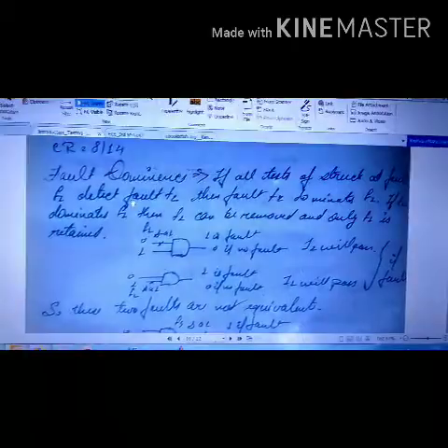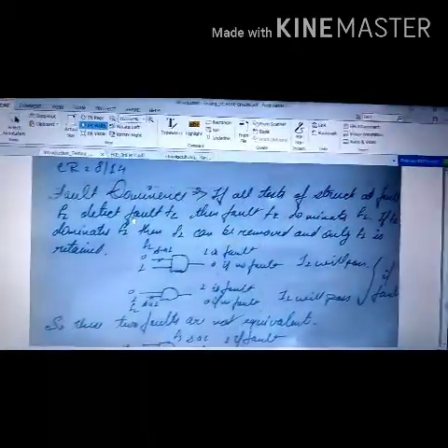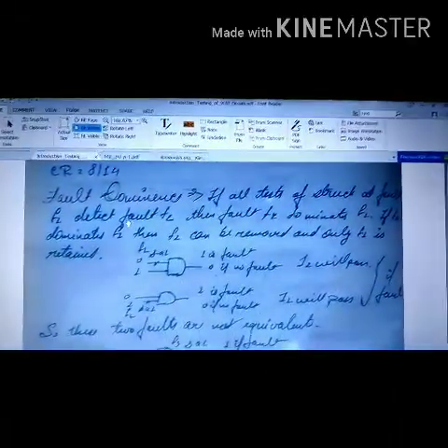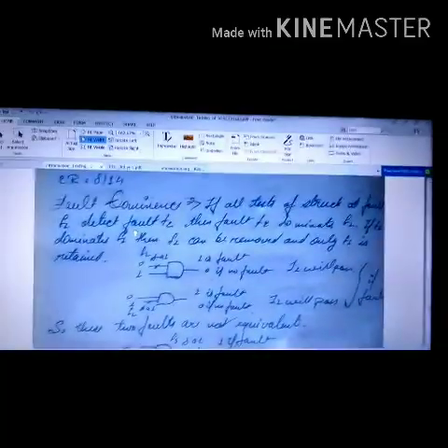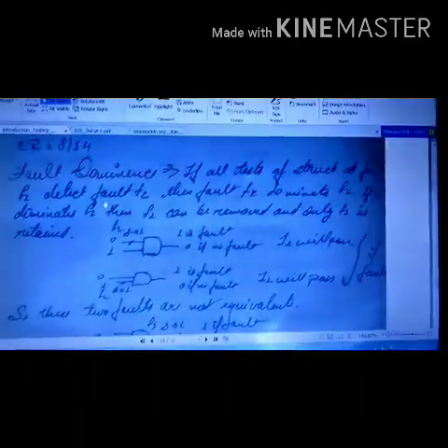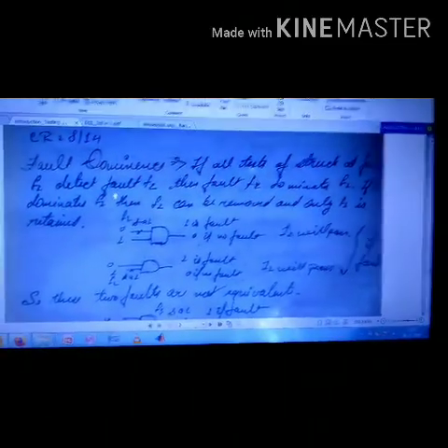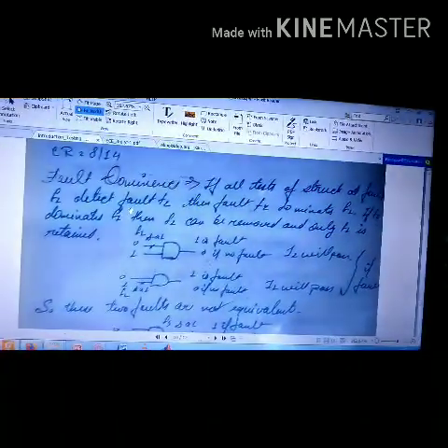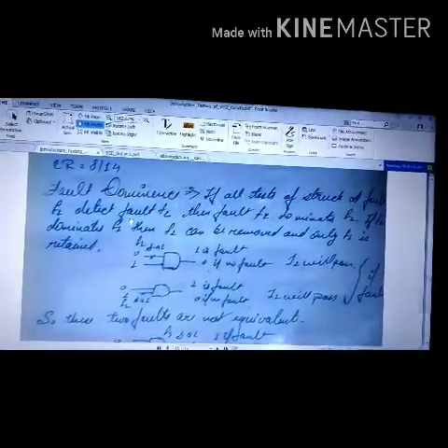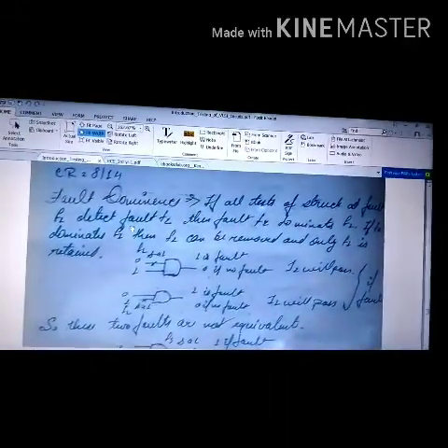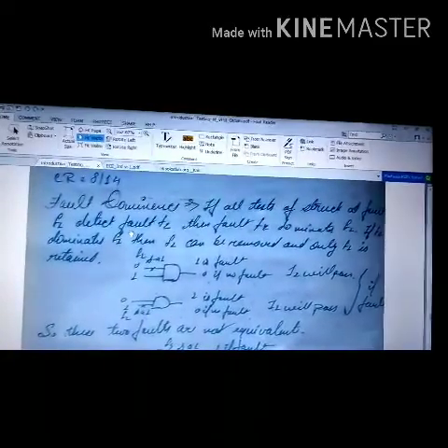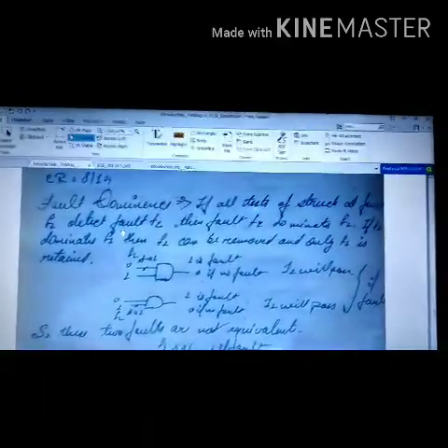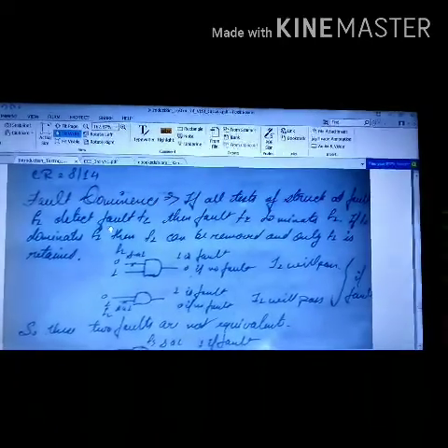Okay, in the previous lecture we had looked at fault equivalence and collapse ratio, and how they can be calculated with the help of an example. Now, in the present lecture we are going to take the topic forward to fault dominance. Till now we have seen that there are many faults which at input and output result in an equivalent answer, and therefore due to fault equivalence these faults are taken as a single fault and they get cancelled. In a similar way there is something known as fault dominance. So let us see what fault dominance is.